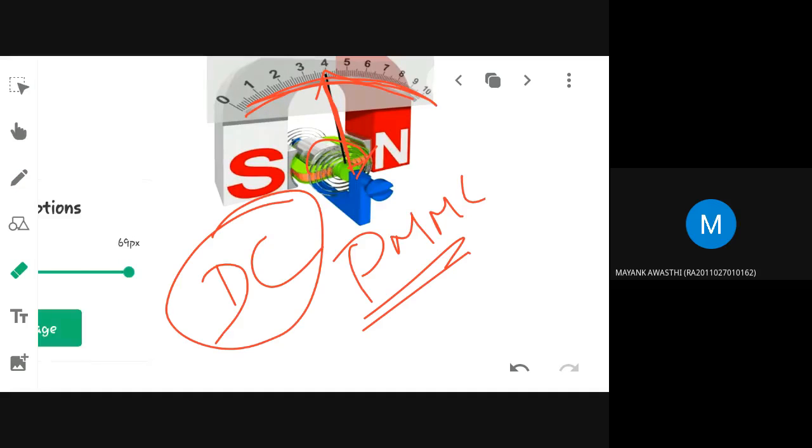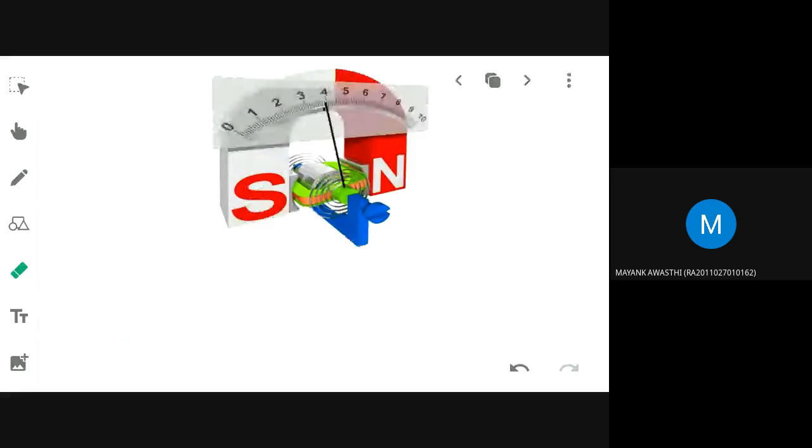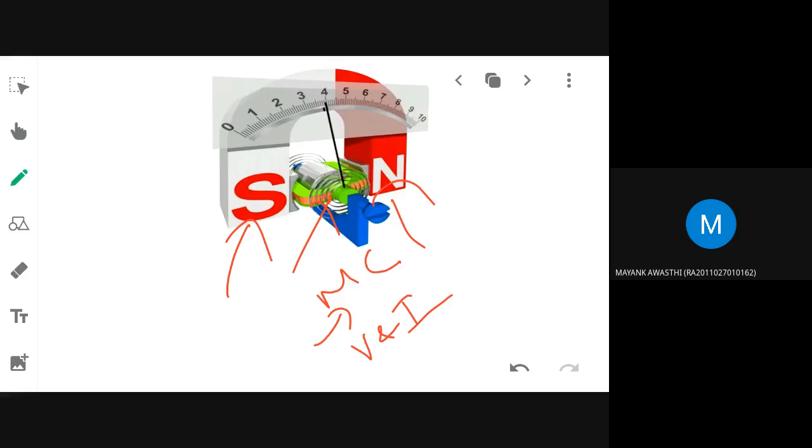Alright. So the name of the instrument is what instrument? PMMC, permanent magnet moving coil instrument. You are going to keep north and south poles, which will be setting up the magnetic field in which you are keeping a moving coil, which is being passed the voltage and current which you want to measure. As a result, a force will be generated that is twisting in nature, which will set this into rotation. With it, the pointer and needle will also rotate on the calibrated scale, indicating the reading.